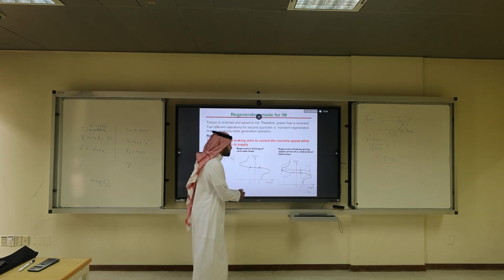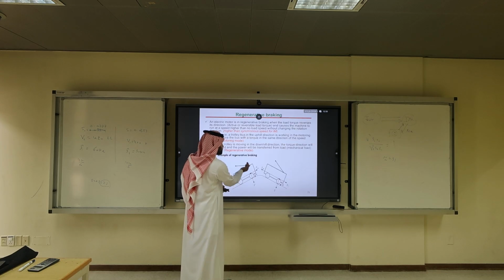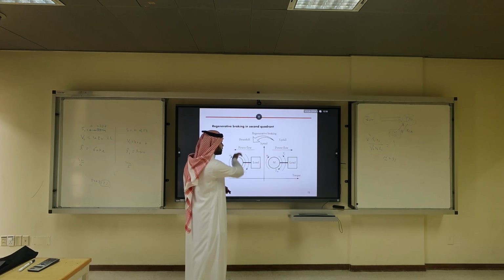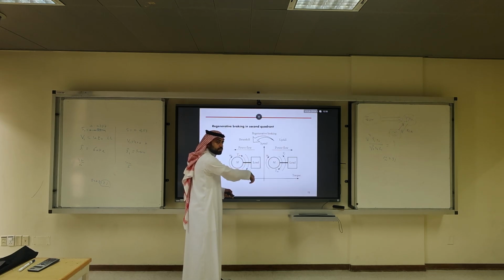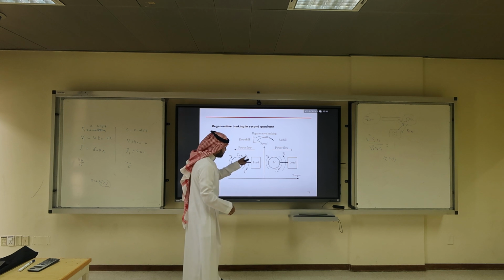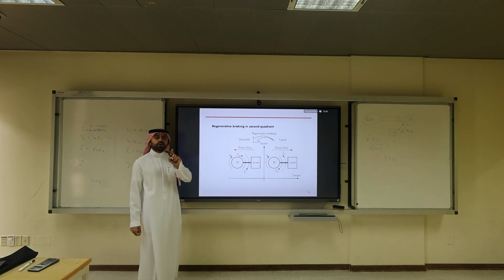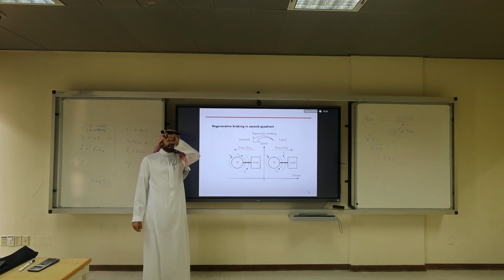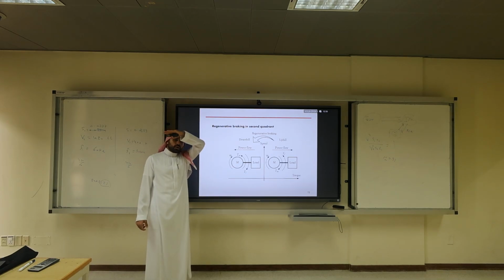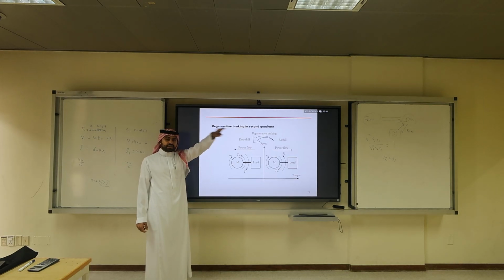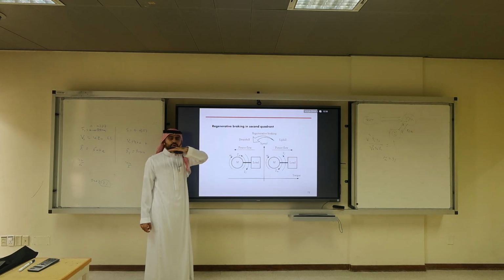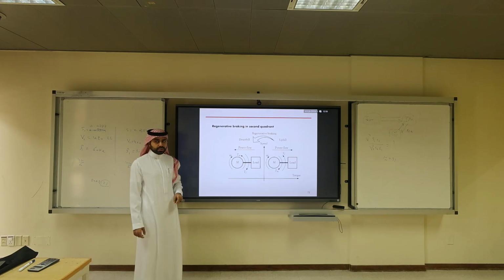In the uphill it was counterclockwise. In the downhill the load became clockwise. This is what we call an active load. When you plot it in the curve, you cannot have it constant torque, 150 Newton. This is the active load, okay? This is the passive load or unidirectional. Unidirectional and it doesn't have negative torque, okay?